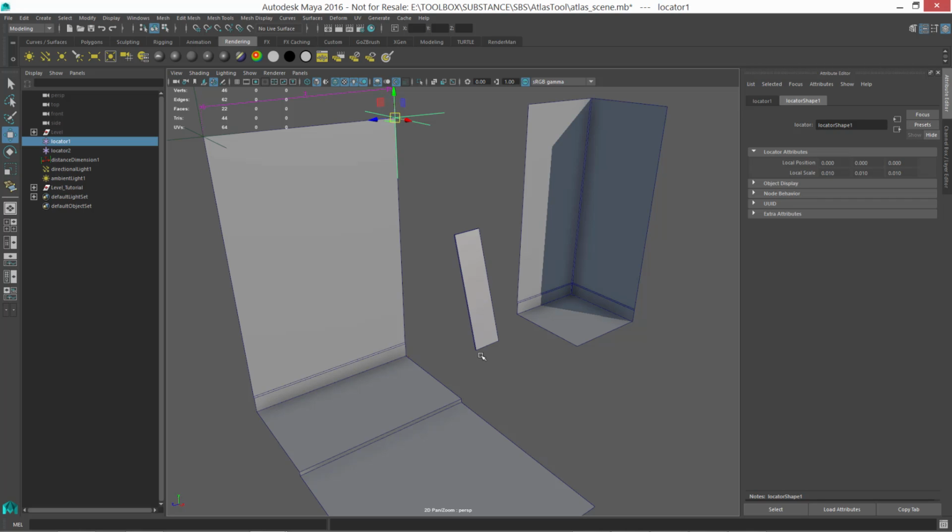Or maybe we could get away with 1 unit equal to 128 pixels. That means that we could have smaller tiles for some of this geometry. It means we can pack more into the texture, which means we're still only using that one texture for all of these materials. Now, I say one texture, of course, as you'll see, it's going to be base color, rough, metal, and so on. It's all going to be several channels that make up that same material. But again, we're packing all this into this major atlas. And so again, it just depends on what your needs are going to be for that.